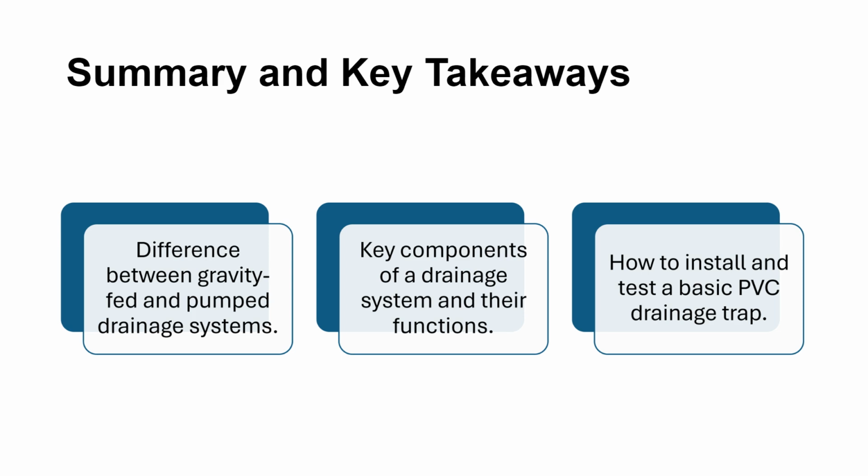You've learned about drainage traps and why they're essential. They keep gases out, protect health, and must be installed with care. You've practiced assembling and testing a PVC trap with clean cuts, proper slope, and strong sealed joints. Drainage is silent, but powerful, and now you know how to build it right. You're not just a pipe fitter, you're a protector of homes, health, and safety. Well done. Module 8 is waiting.